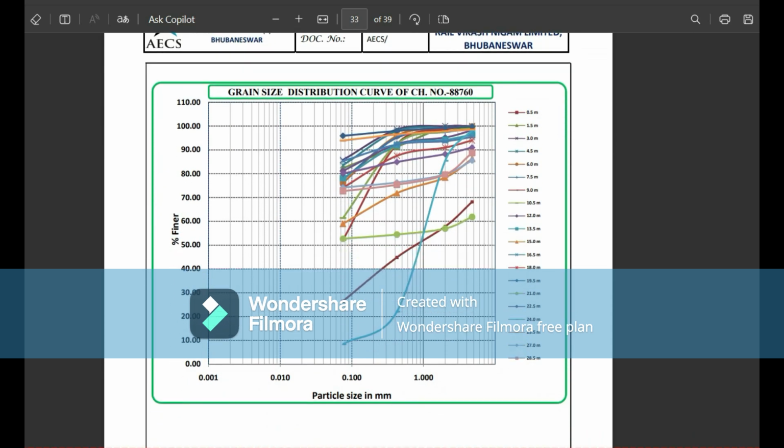Also grain size, particle size, and percentage of fines change as per depth, with different colors and different types of markings. The soil grain size curve is a semi-logarithmic curve, which visually clarifies this.